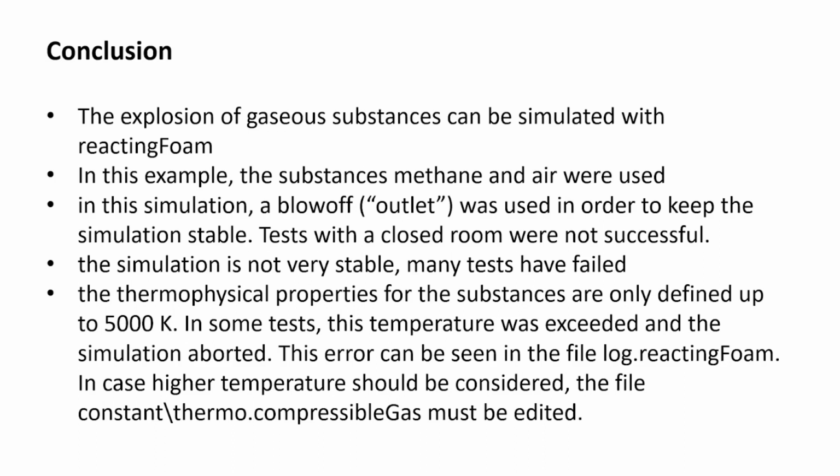And the last point is that thermophysical properties for the substances are only defined up to 5000 Kelvin. In some tests, this temperature was exceeded and the simulation aborted. This error can be seen in the file log.reactingFoam. In case higher temperatures should be considered, the file thermo.compressibleGas must be edited.